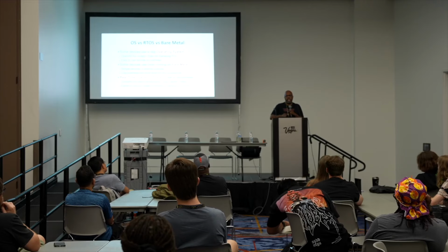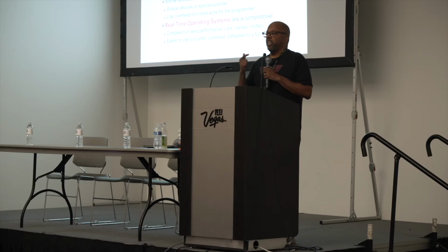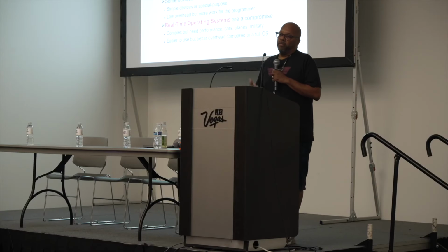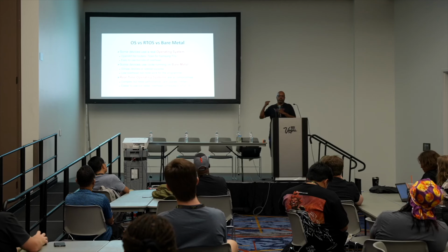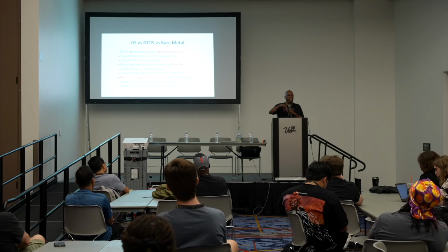So if you have some task that needs to be performed, like, I've got to sample this audio signal 8,000 times a second, right? And you've got to meet that deadline no matter what. A real-time operating system is the way to go, because it'll make sure that it interrupts everything around that deadline. You know what I mean? So they have scheduling algorithms that they use to support that.